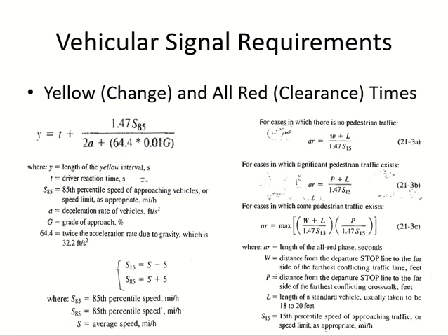You can see we are not using any traffic data here. No volume, no flow rate. We are using time. Which time? Perception reaction time. Do you remember anywhere else you have used perception reaction time? For calculating what? What did you calculate? Stopping sight distance. Yes. So perception reaction time is used for calculating the sight distance.